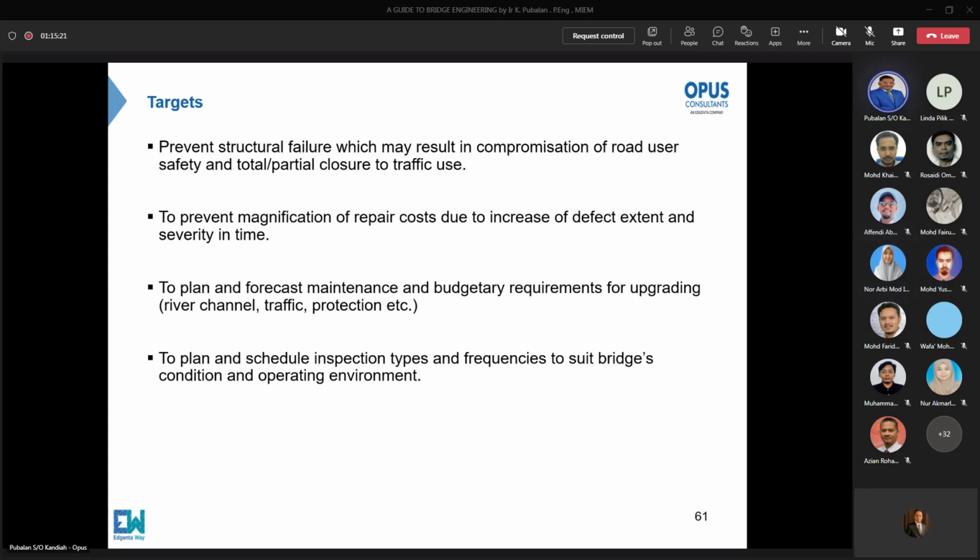So RB, it's important that the inspector has either a certificate or a diploma. If they have neither, they must have some experience, because we can't deny those people who do not have the papers but have a lot of experience. Maybe the guy worked in the JKR Bridge Department for 10 years. He's still fit to do the inspection. It's okay. But when the defect rating is higher, the person with 5 years experience must come down.